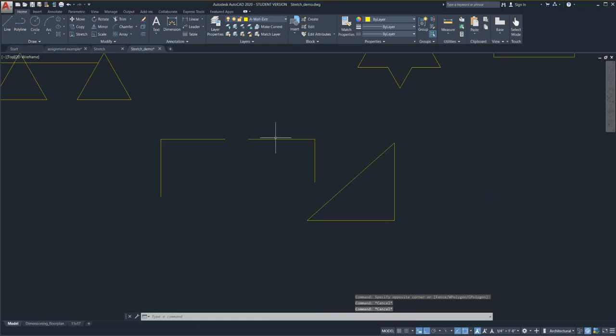Okay. Here is another example, one line, escape, two lines, escape, p-edit, enter. Okay, I can click on multiple or just hit enter. Select my lines, hit enter, and I want to join. Obviously it's here, but I'm very used to coming down to here. Join, click, enter, enter again, and we're done. Okay, so that is polyline edit.